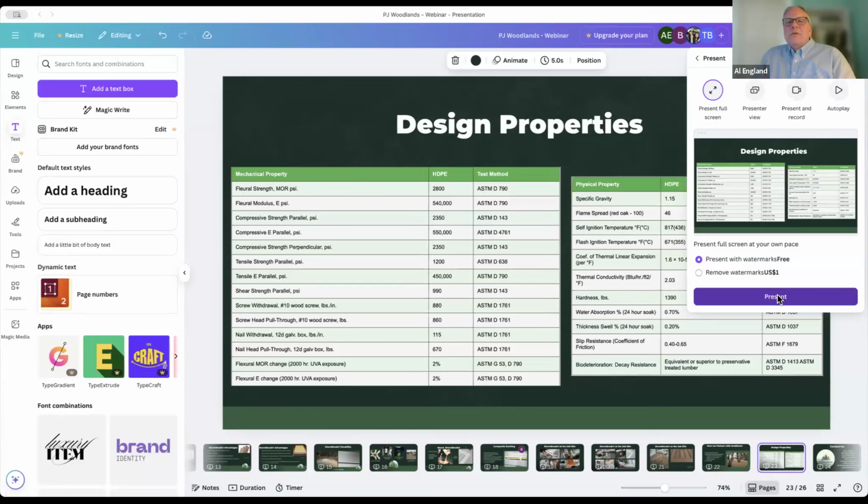The other thing to keep in mind is 3 or 4 years after wood has been exposed to the elements, its structural properties are not what they were originally when they came from the lumber mill. With this product, they are. So that's really the difference as far as performance of wood versus these other products, and that's before you have any pest issues or rot and decay issues or moisture absorption issues that we'll typically see with lumber products or engineered wood products.